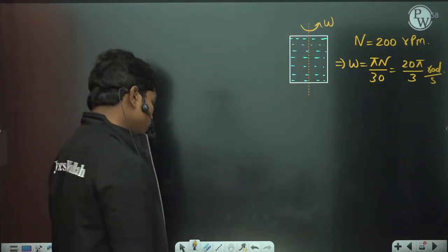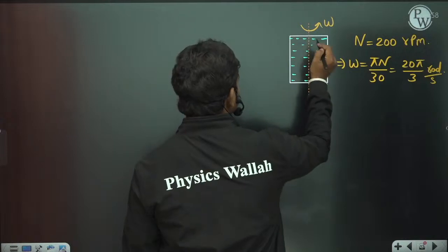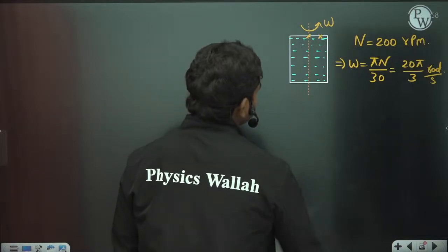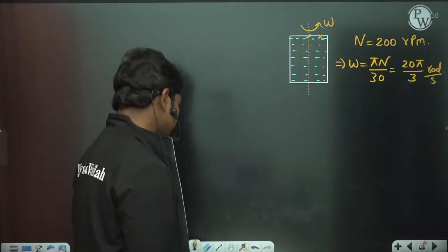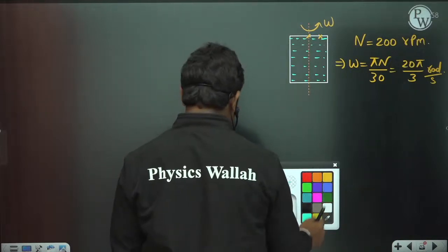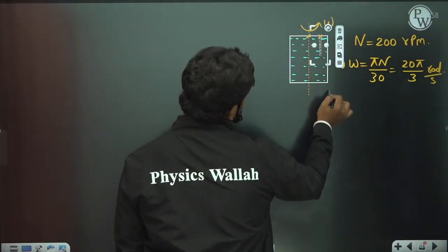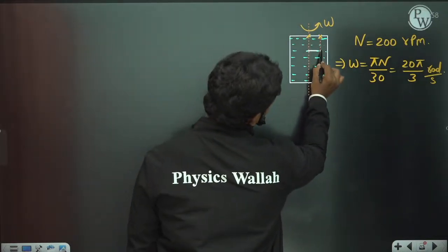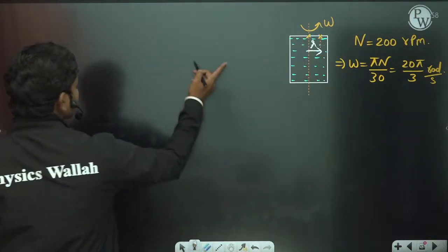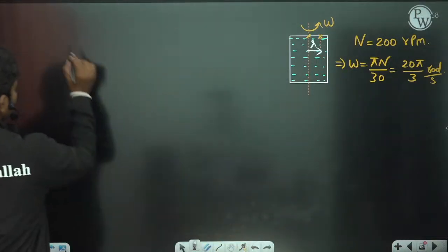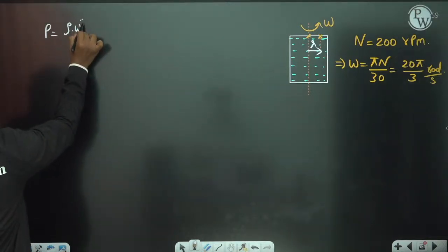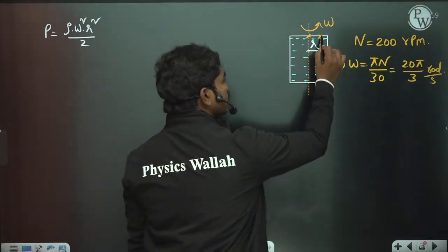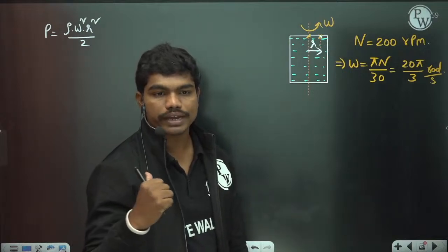Now whenever this is rotated, it's basically a forced vortex. If you take the pressure difference between two points, at the center the pressure is 0, because the radial location is 0. At any smaller radius r, the pressure P at that location is rho times omega squared r squared by 2, as we have just seen.